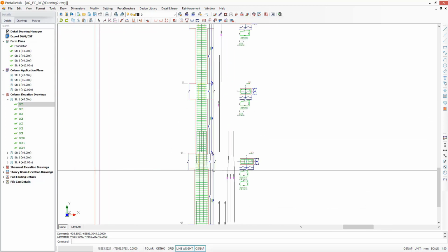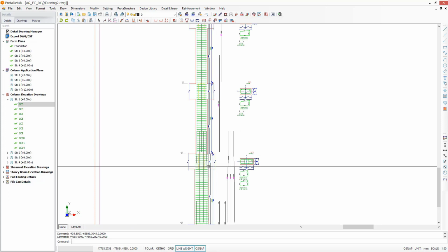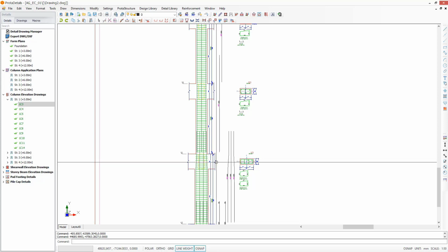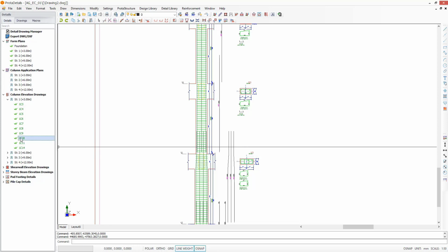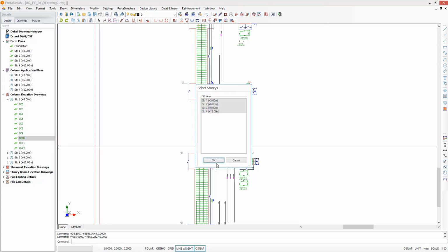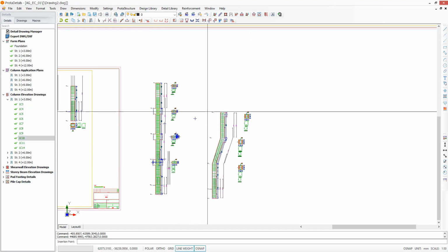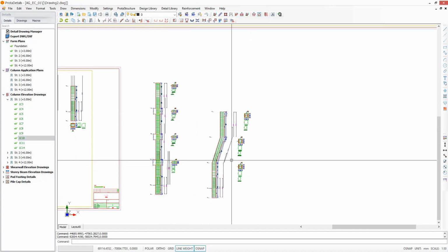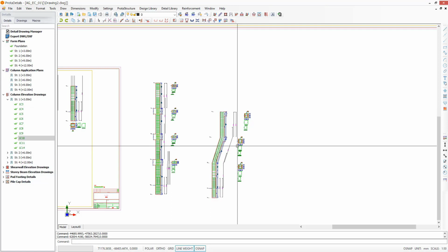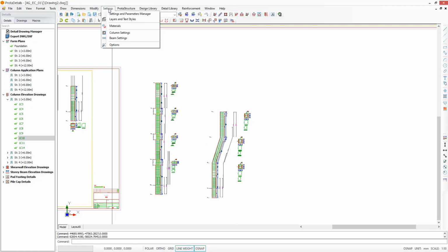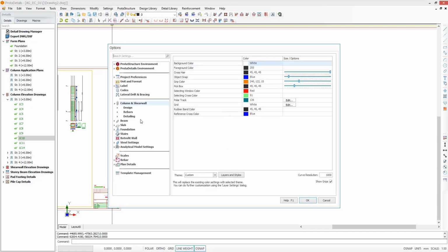And you can actually see the section changing, and all rebars are bent according to the code provisions here. Well, of course, it can also handle slanting columns. For a slanting column here, as you can see, it follows the path of the column very precisely. But there are many more options regarding the column detail generation, and you can all review them here.